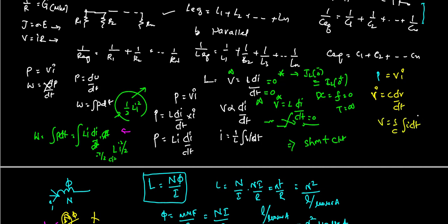Let's see what happens when t equal to 0. It would require an infinite amount of current, and infinite current is impractical. That's why the voltage cannot change within zero time. In a capacitor, voltage cannot change within zero time. Whatever the voltage before the switching action, that will continue for some time after the switching action. This has to be remembered. It is an important point for transients.